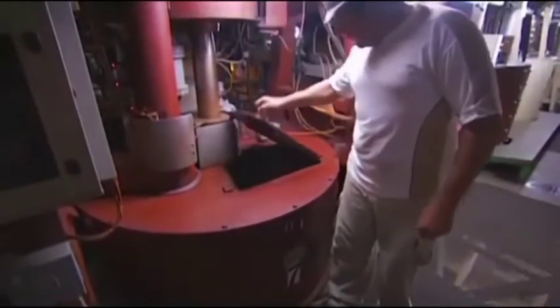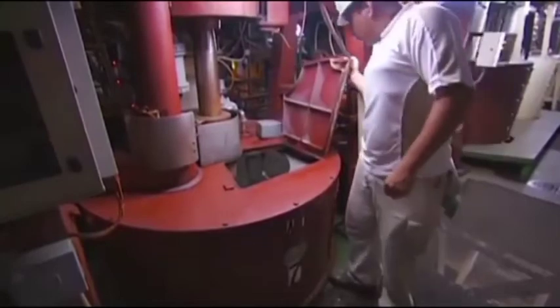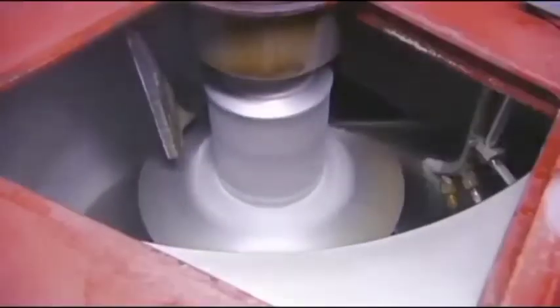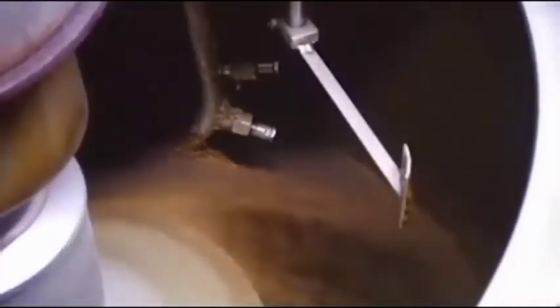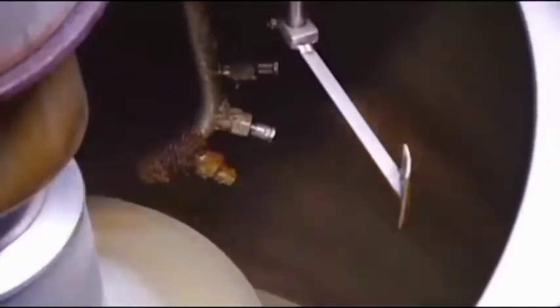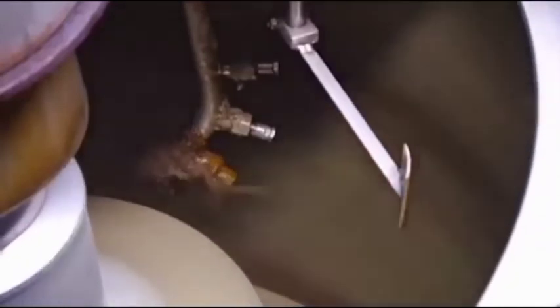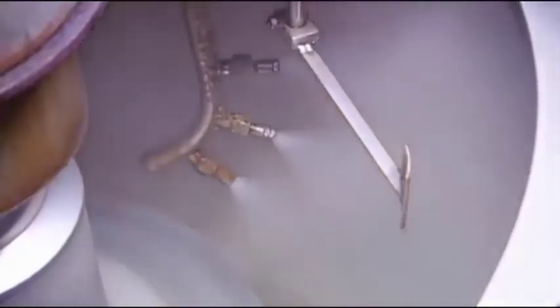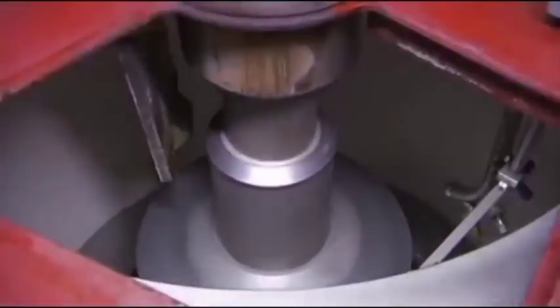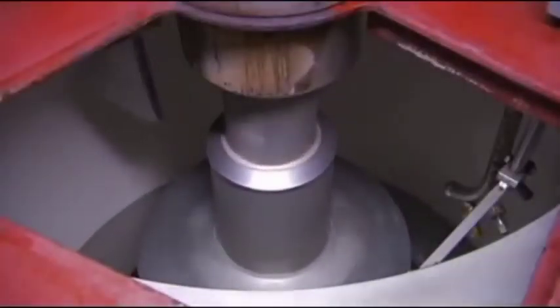Another additional groove that is commonly used is the chevron groove, which is an additional groove that cuts across the existing groove to form the letter V. The depth of the chevron groove is almost the same as the cross groove. The distance between the grooves is 20 until 25 cm. The purpose of chevron grooves is to improve feeding, usually used on top rollers and face rollers.